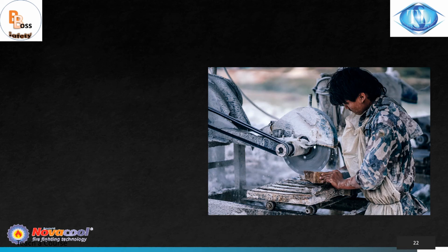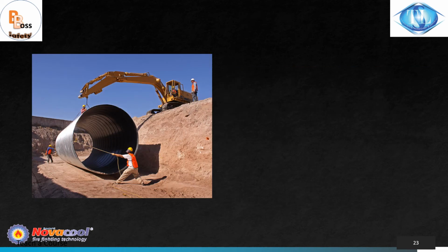Okay, this is the first image. You should identify the hazards and see the loose clothes that can be caught in the rotating blade. There is nothing to stop his hand from sliding. There is a lot. There is no proper guard. You can see the belt. There is a guard for the blade and it's not complete, but there is no guard for the belt. So you have to find out. I'm just helping you with the first one.